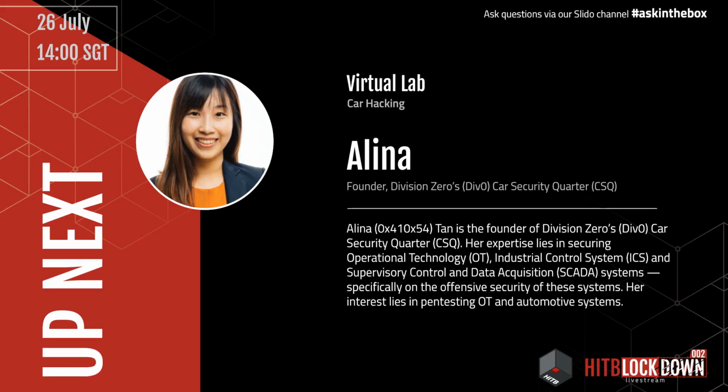Okay, so we have a new question. How do different modules in the car authenticate each other? To answer this, CAN bus and LIN bus, like I've mentioned earlier, is a broadcast network. So think of it like UDP. They don't authenticate each other. It's a blast and you receive all the messages on the other end.